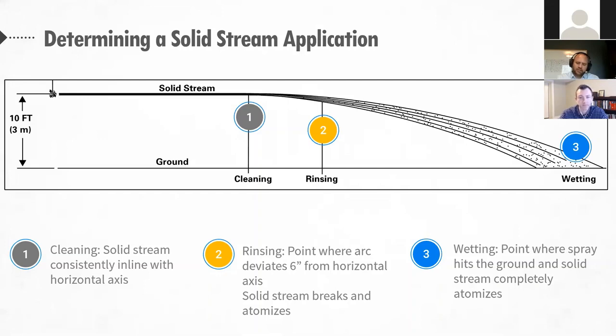Yeah, and Kyle, the critical piece on the solid stream nozzles is understanding what your goal is and how to leverage the physics behind what's happening, like you said, for debris removal or a descale closer in. However, if you want to get some good wetting and good coverage, you can position that nozzle a bit away and get some good rinsing effect with the solid stream nozzle, while maintaining a certain level of that energy versus just using a flat fan. So yeah, that's a great point. The cleaning, rinsing, wetting idea. Yeah, that makes a big difference if you're trying to clean something that's really stuck on versus you just need the water to rinse off the surface or even just fall onto a surface. Yeah, thanks, Kyle. Mary, next slide.